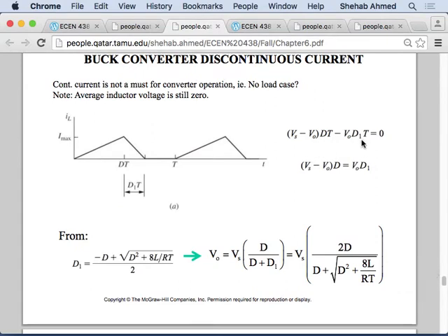It's some time duration, D1. This is happening during some time duration D1, right? So the switch is on for d. It's off for 1 minus d, I agree. But there's current flowing only until D1 times T. So current falls down to 0 after D1 times T. So this is how you will get your voltage transfer equation, not from the 1 minus d. These are the two areas that are equal to 0.